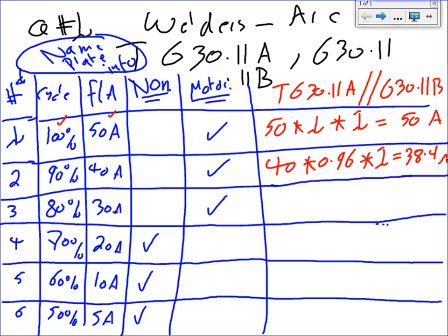Okay, let's go down to the 30 amps. Let's look at the cycle. The 30 amp has a cycle of 80. Is it still motor? Under motor, 80 motor, 0.91, right? Everybody see that? Where did I come up with 0.91, Mr. Erbab? This is coming from table 630.11a under motor generator for an 80% cycle motor generator arc welder.